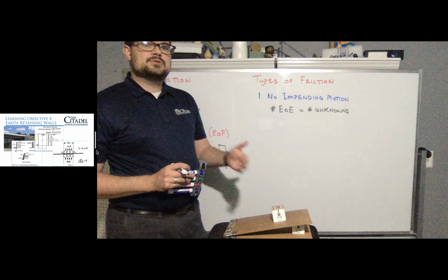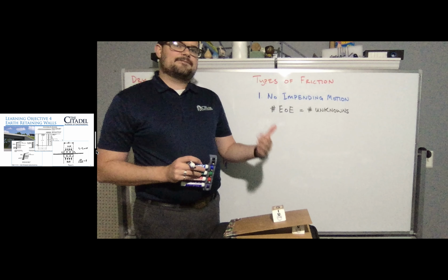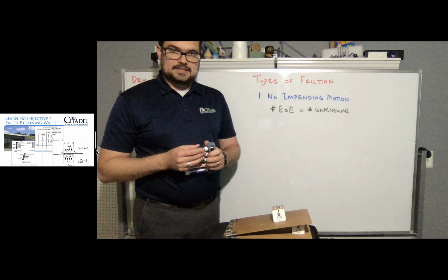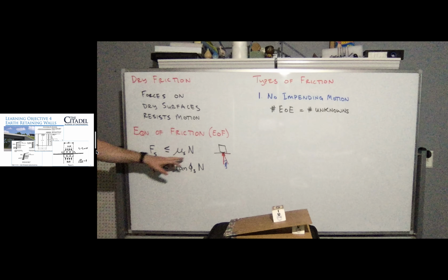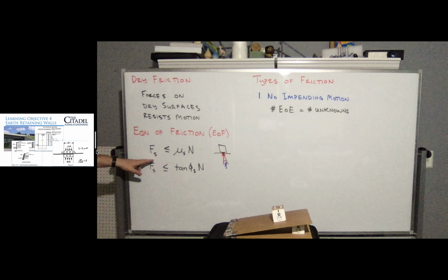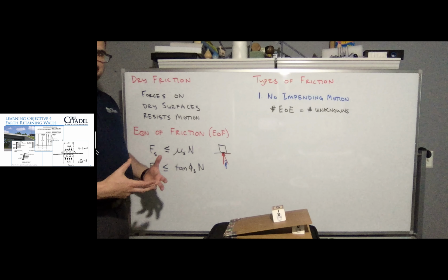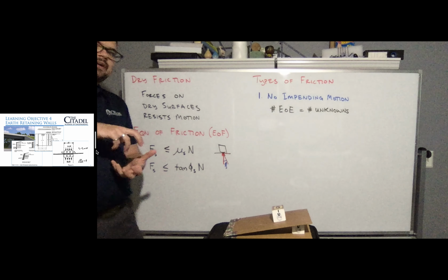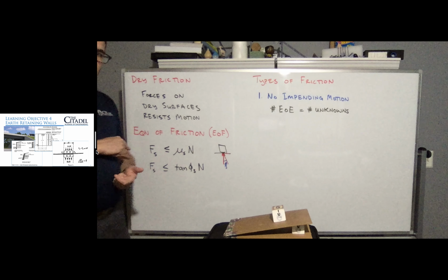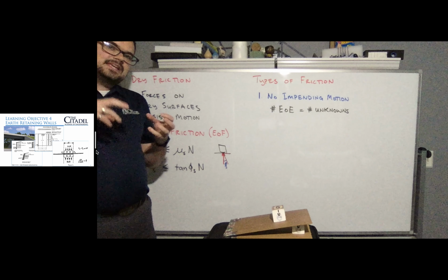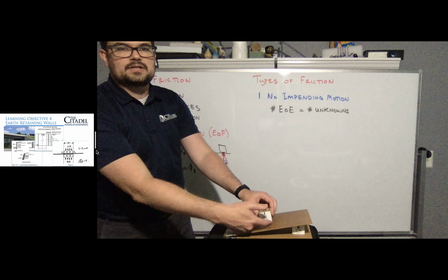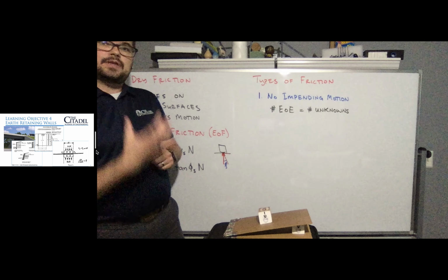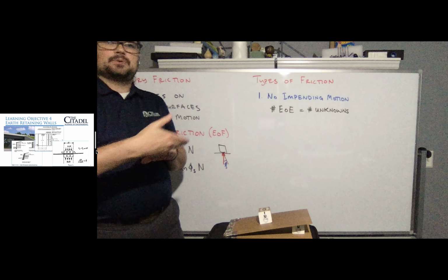If we use moments, we can actually calculate where that frictional and normal force lie, the centroid. If we look at this equation over here, we'll notice that the relationship between the normal force and the frictional force doesn't have area in it. The contact area doesn't change this relationship. What it changes is the intensity of the distributed load. There is a distributed load acting across the bottom, both a normal pressure and a frictional pressure.